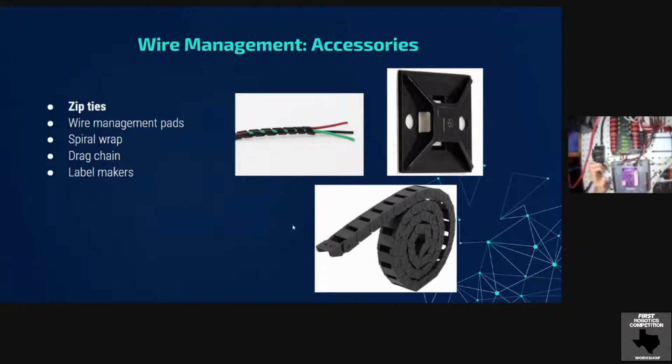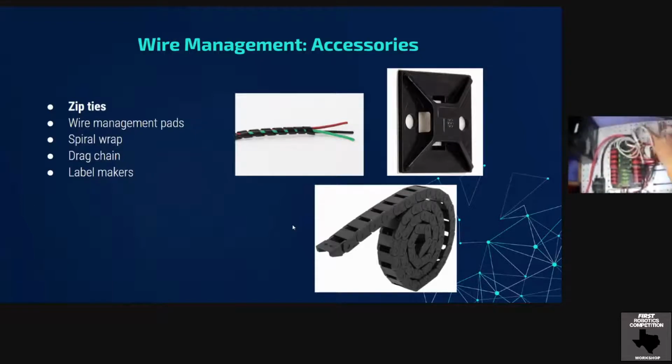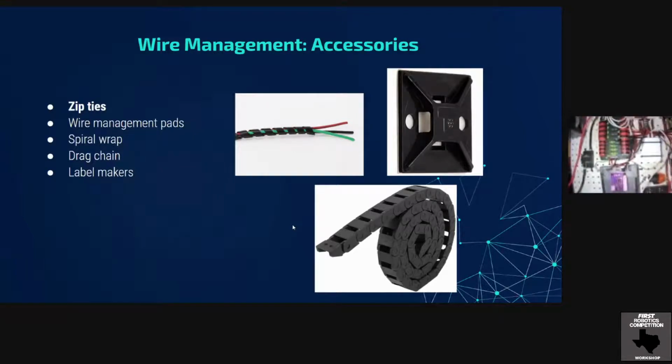The other thing is things like solenoids. So way back here, I've got my solenoids. This should always be zip tied down, because if you need to add additional pneumatics or anything like that, you're just going to want to be able to take that off and then put it back on. And motor controllers, if your motor controller is starting to have problems or you need to take it off to rewire it or whatever, just zip tie, zip tie, zip tie. Don't screw anything down. You can use Velcro, but that's a lot more expensive than zip ties. So just keep that in mind.